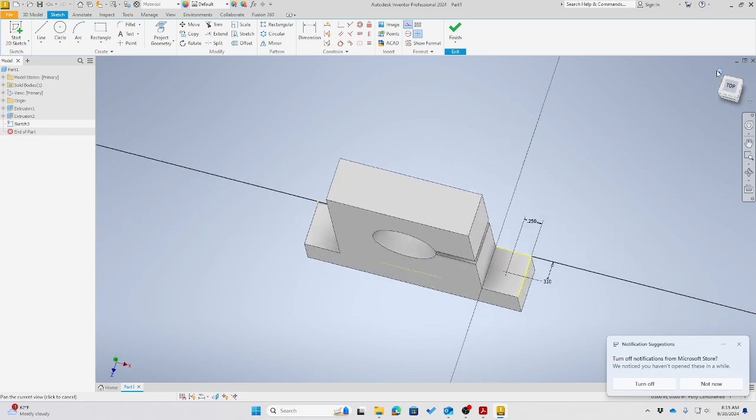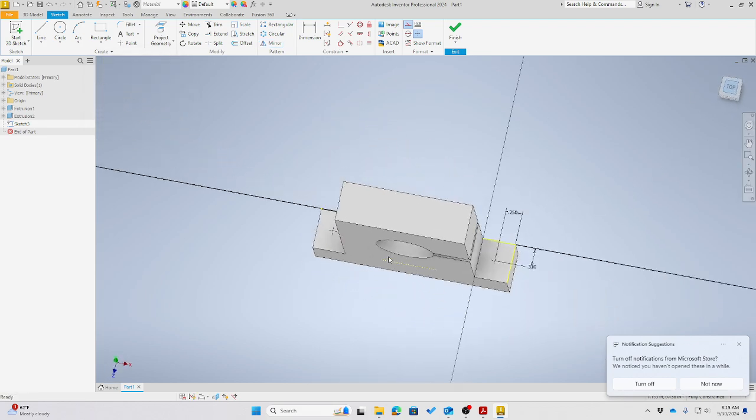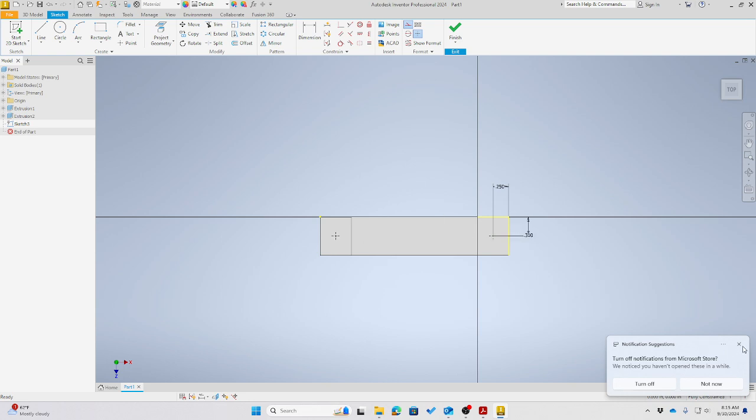So now let's look at the home view. This is the construction line we need. You see that this is the construction line we needed to mirror this one. So now let's go to the mirror, select the object, the point we want to mirror, then click on the mirror line, move the mouse and find the construction line, click, then apply it. So as you see, done. We have now 2 points. I mirrored this one to this location using this construction line.